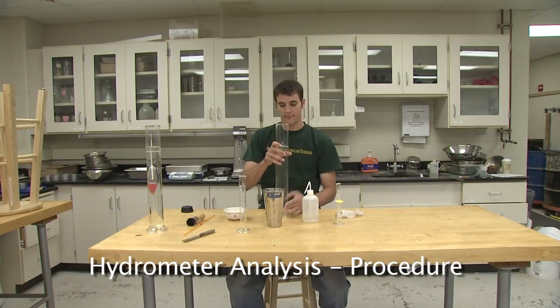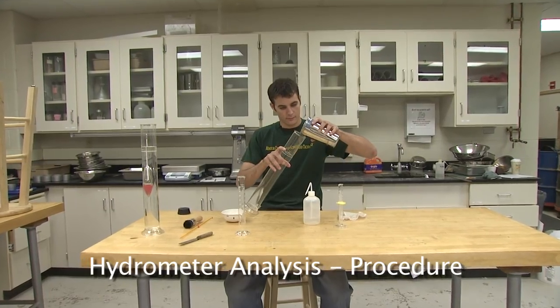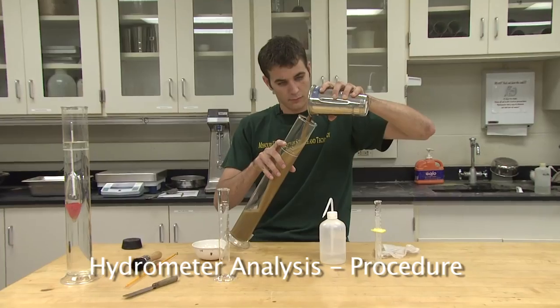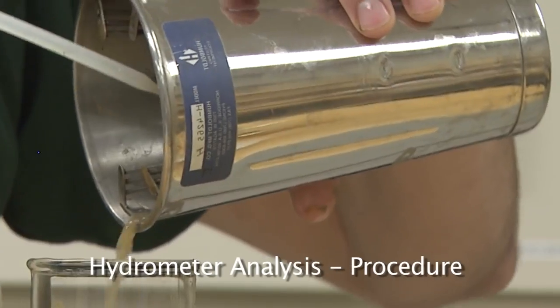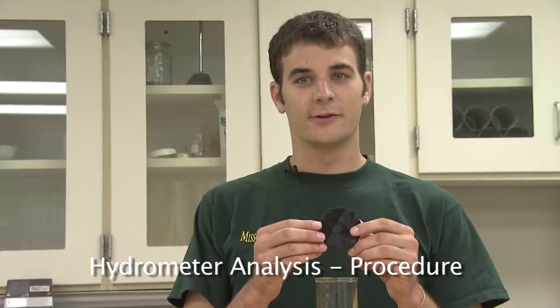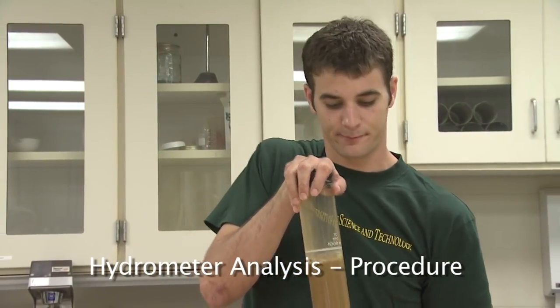Pour the sodium hexametaphosphate solution from the dispersion cup into a clean sedimentation jar. Again, using a squirt bottle with water, ensure that all the sediment has transferred from the dispersion cup into the sedimentation jar. Cap the cylinder with the rubber stopper. Agitate the solution for 1 minute by turning the cylinder upside down and back 30 times in 1 minute.